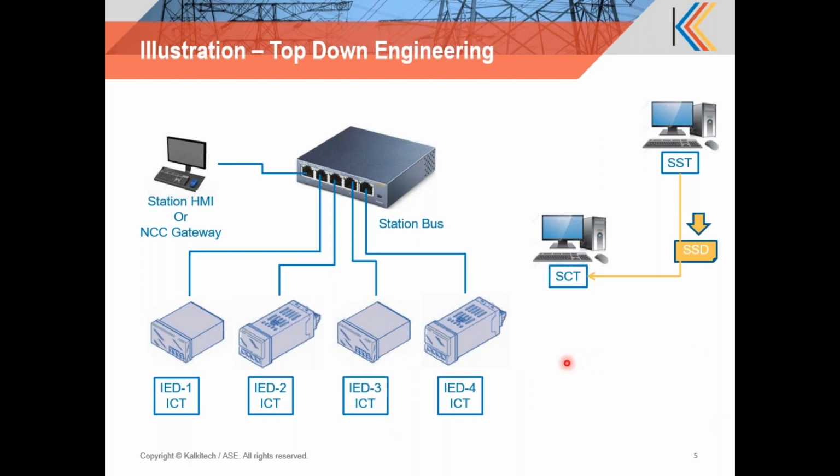So the user now imports the ICD files that are generated by the ICTs into the SCT, and he then performs the core configuration of the system. That is, basically he has to name the IEDs, give them a context, assign network addresses, map the functions from the specification, the single line diagram in the SSD file, to the IED, create data sets to set up the communications, create reports, report control blocks, GOOSE control blocks, and he has to map the signals between the IEDs, IED to IED signal mapping in the case of GOOSE, or from the IED to client for reports.